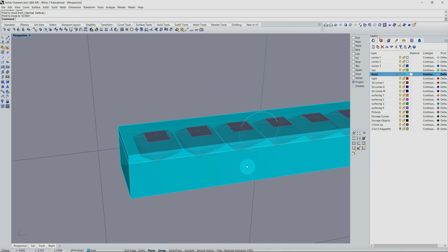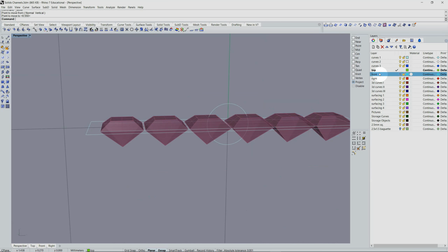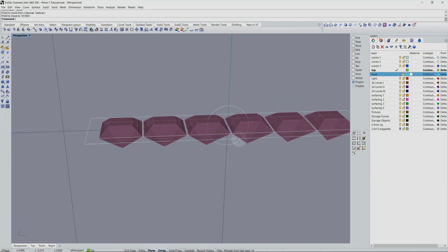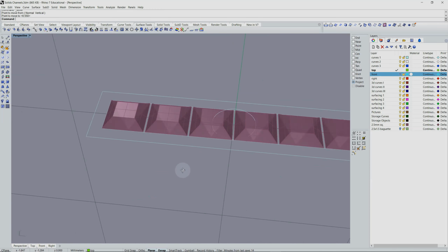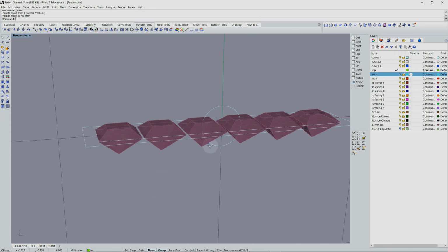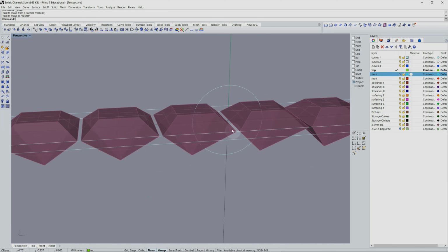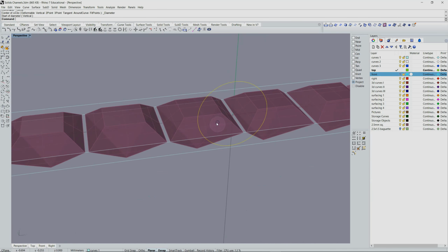Next, we need to create the two interior support bars. I'm going to place these bars on either side of the two center stones, here and here. To help find the location for these support bars, I'll use the same reference circle that I drew when centering up the stones. I'm going to copy this circle into location using the Copy command off of the Transform tab.